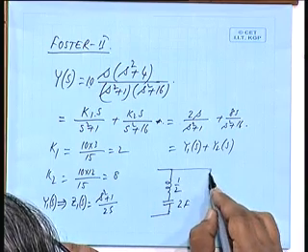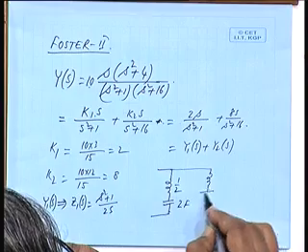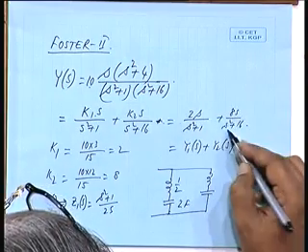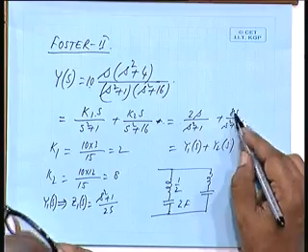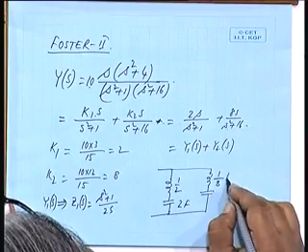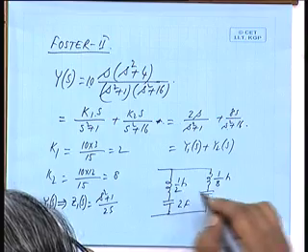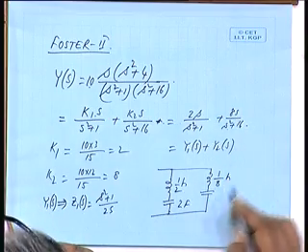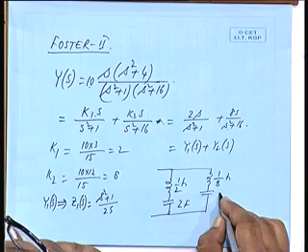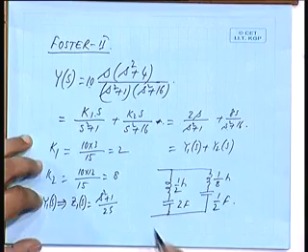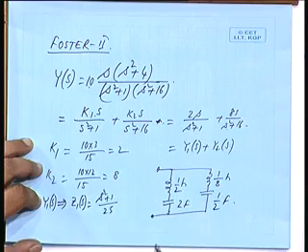Another combination, Y2(s). How much will be the element values of Y2(s)? Invert it: (s squared plus 16) by 8s. That is s by 8, which is 1 by 8 Henry, and 16 by 8s, so 2 by s, which gives me half a farad. Yes. Is that all right?